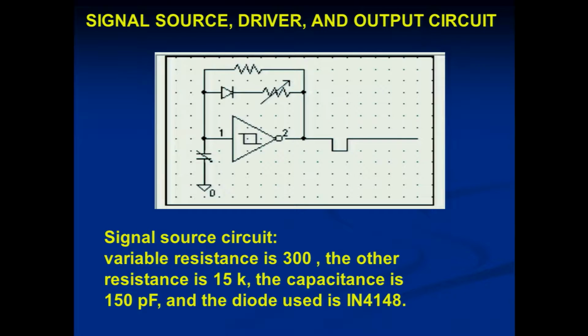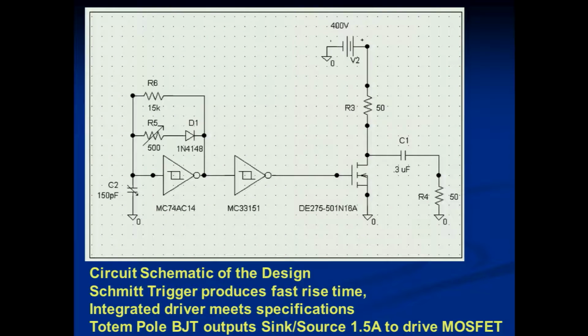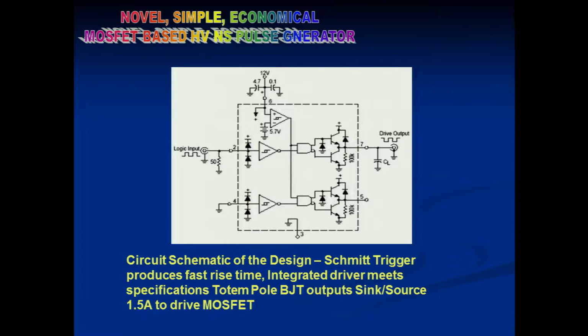So you do a design before you build it. He did all the design. If you see this paper, you have everything, you can reproduce it. And then he used the schematic concept, this is the symmetrical concept, this is the driver which will go onto this MOSFET, which will discharge into this. This is the source of the MOSFET. We used an auto transformer for a 0 to 400 volts variation. Everybody knows an auto transformer? Again, he had one from somewhere, he brought it. This is the whole schematic.